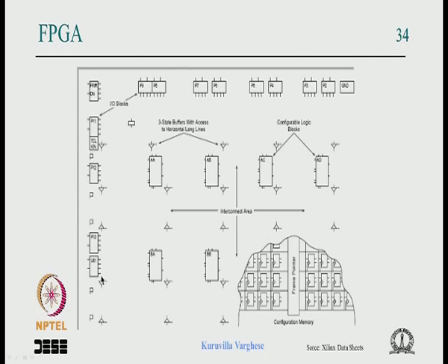In FPGA, as we have discussed, there are a lot of combinational circuits and flip-flops. So there will be lookup tables, flip-flops, interconnection, wires, switches and all. But then you know that all these need to be configured, like switches need to be programmed on or off, the logic blocks need to be configured and so on. So there is a lot of overhead configuration circuitry, that means the configuration pattern needs to be stored somewhere. At power on these switches need to be programmed and so on.